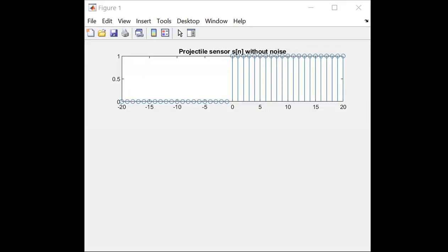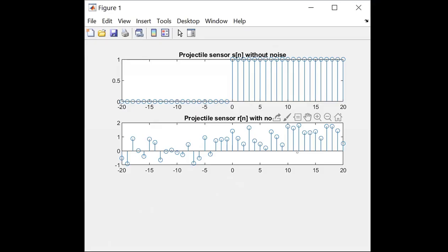Okay, so as a quick MATLAB demonstration of this, here's our projectile signal. If there was no noise, no dust signal, when we add the dust signal in, this is actual data that was computed on the fly. This is our signal up here, u of n, to which I've added additive white Gaussian noise. And you can see in general on the right, it's higher than on the left, but you'd be hard pressed to say exactly when to pull the trigger and have your round explode.